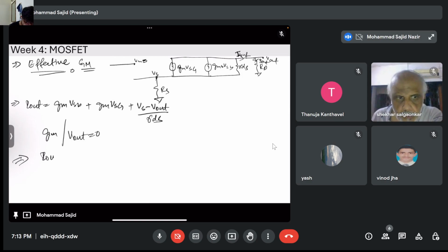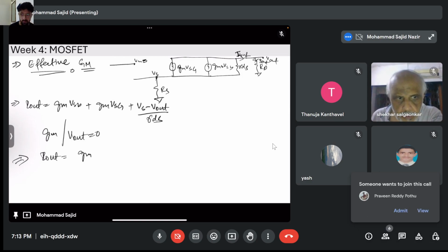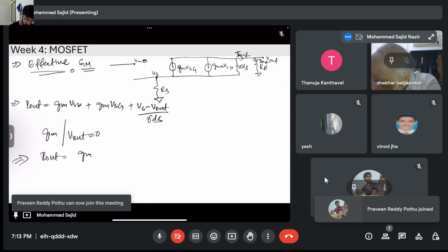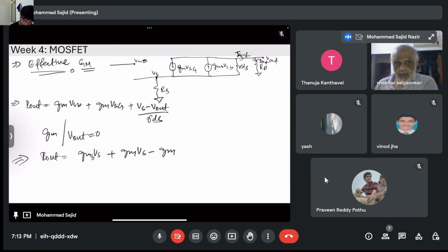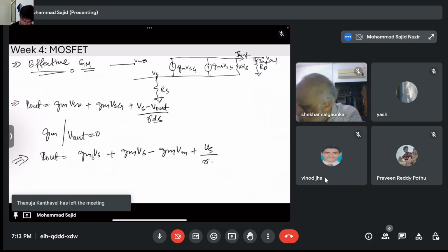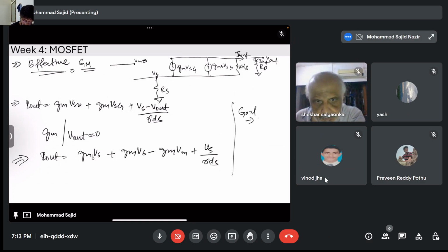So I output will be Gm times Vs, because Vb is 0, plus Gm times Vs minus Gm times Vin, plus Vs by Rds. Now the goal is to calculate I output by Vin, right?